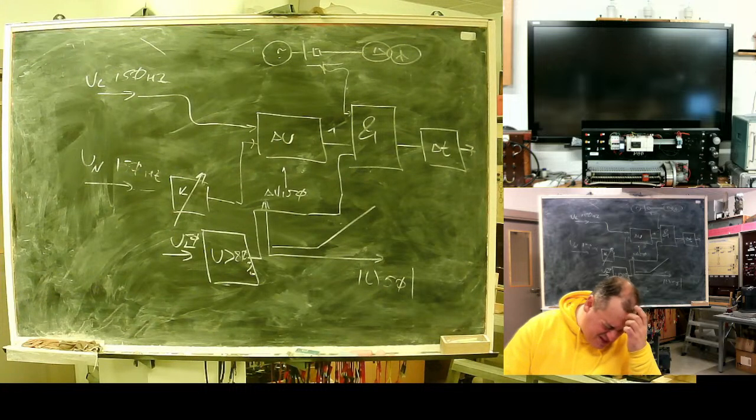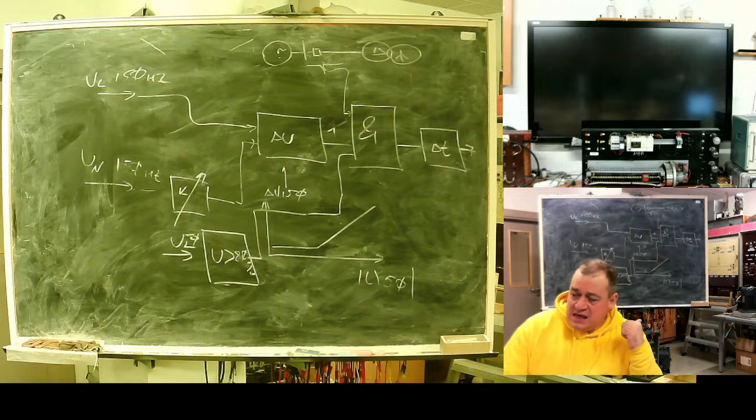To prevent misoperation in transients, use good practice for such protection: set time delays of about 1 second. To prevent misoperation at the moment when the generator is excited.